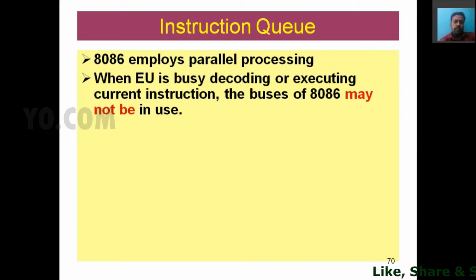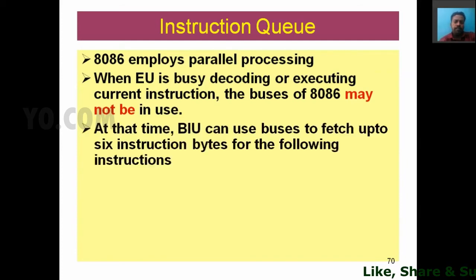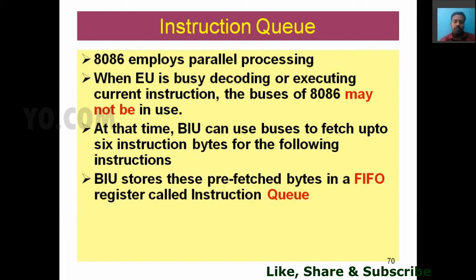At that time, the bus interface unit can use the buses to fetch up to 6 instruction bytes from the following instructions and store them in the instruction queue.